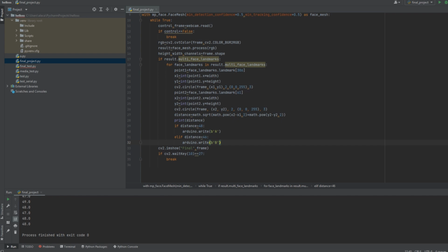So how can we fix this error? Actually, fixing this error is very simple. For this, it will be enough to make a small addition to our Arduino code. What we need to do is to clean our LCD screen before the setCursor function in our conditions. In this way, we can achieve the desired result.